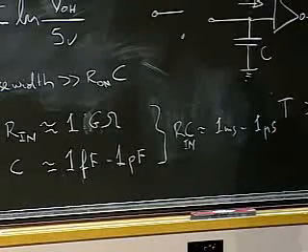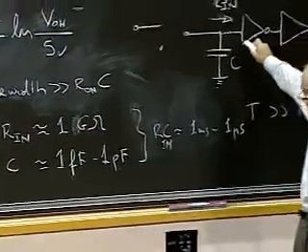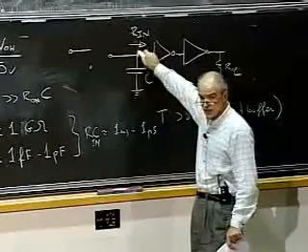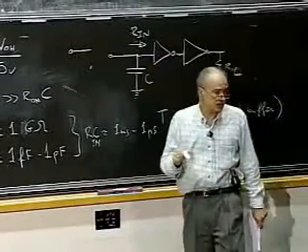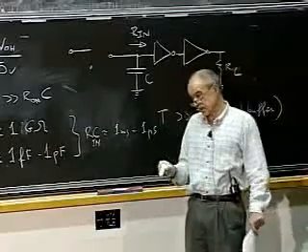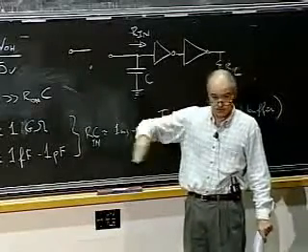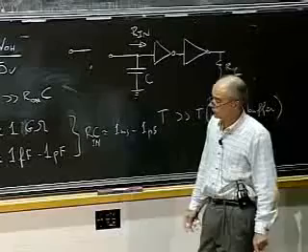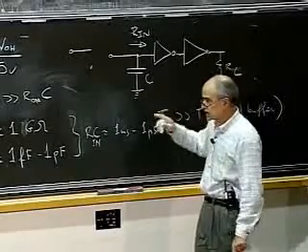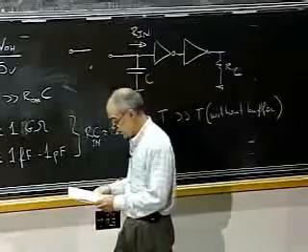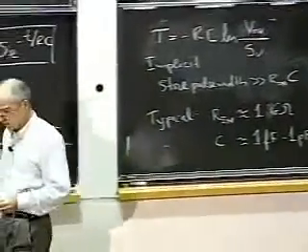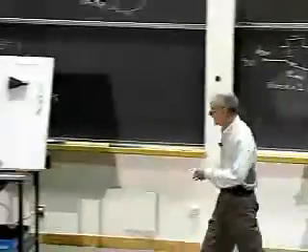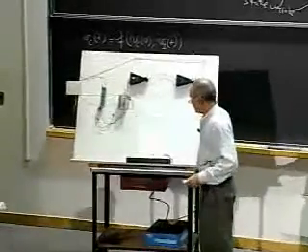So if I have this kind of circuit, somehow there's got to be additional circuitry that comes back, samples the voltage here, and restores it. And that's actually what is happening in a DRAM. My laptop is working there, and its DRAM keeps getting refreshed every, say, a millisecond or whatever the condition is. Okay? But in our case, we're going to do a slightly different case in which we will create a static memory.